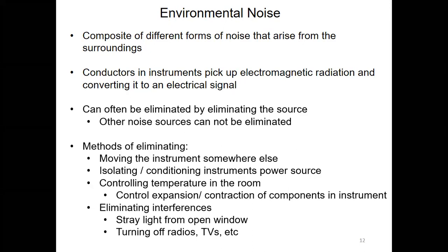And also we can isolate or condition the instrument power sources. That means sometimes instrument power sources, when they get older, will generate lots of noise, huge noise. You will hear it when we turn on the instrument. Sometimes much noise is there, and vibrations.